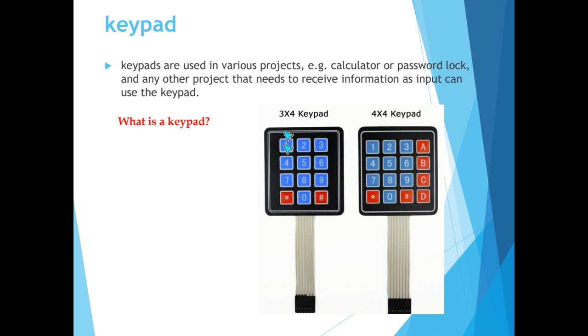You know that it includes 12 keys, and if we don't use a keypad and want to use ordinary keys, we should use 12 keys interfaced with the microcontroller. Then it would be required to occupy 12 pins of the microcontroller with our keys.